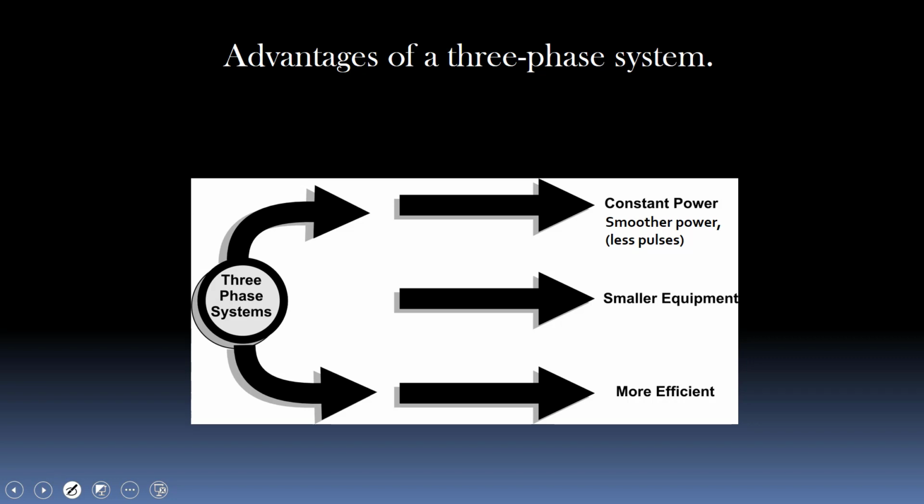Now, the other thing with that is we don't really require any special starting for the most part on a 3-phase motor. With a lot of single-phase stuff, you'll have a start winding or a start capacitor, extra windings that might come out of the circuit after it's running, and they're needed to get that motor going. With 3-phase, we don't need that. We can just apply voltage directly to the 3 windings, and it creates that rotational torque to get it going.